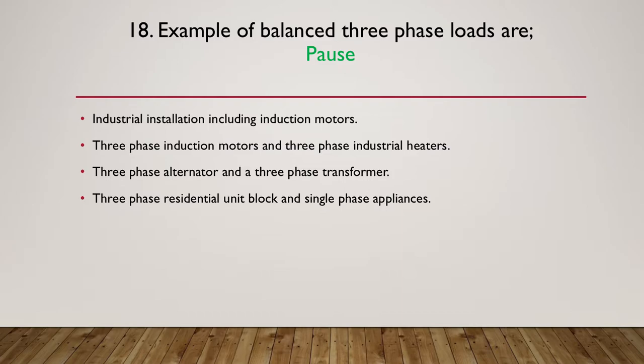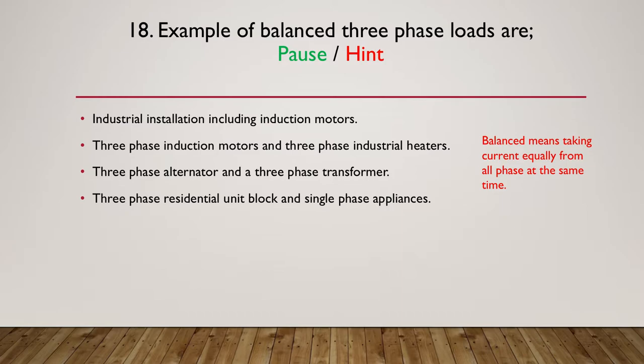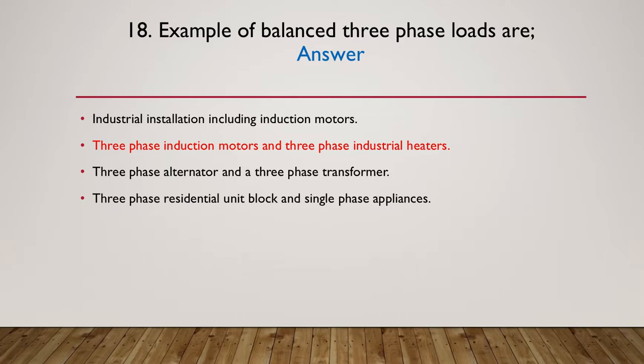Okay, time for our hint. So balance means taking current equally from all phases at the same time. So on our list here, which ones would be taking current equally from all phases at the same time? So let's move on to the answer. The only one that fits is three-phase induction motors and three-phase industrial heaters. Is the only correct answer.